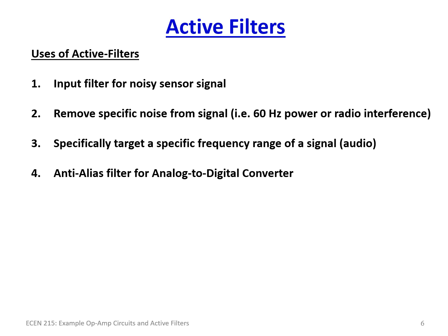So you have to put a low pass filter in front of your analog digital converter to reject or get rid of these high frequency signals. Otherwise you end up receiving something that maybe looks like a real signal, in which case it's actually fake. And that can cause all sorts of problems in embedded control systems. So you basically put low pass filters on your analog digital converter.